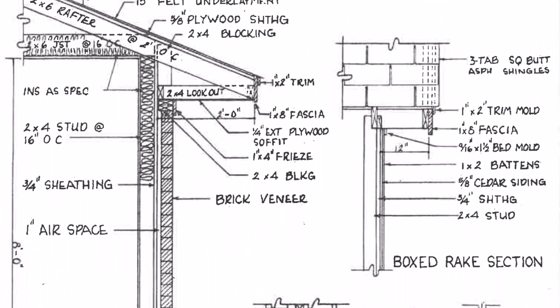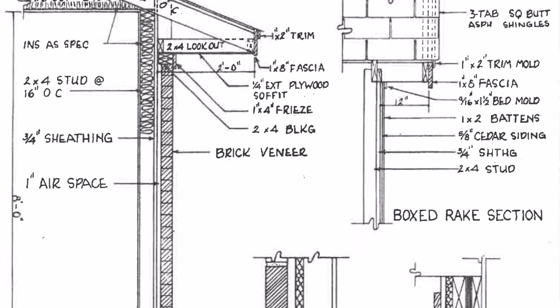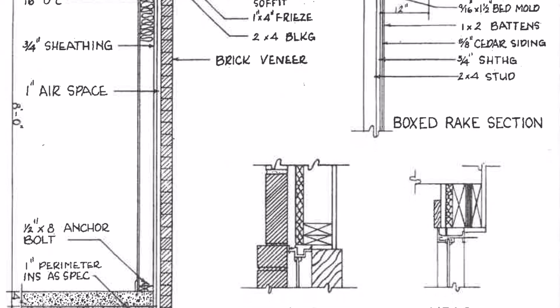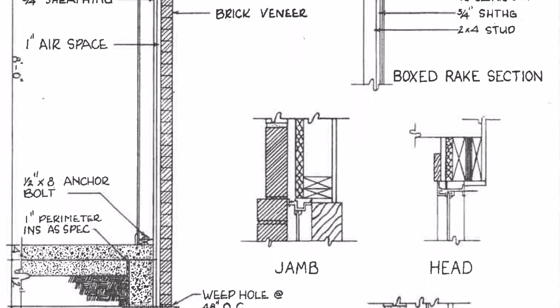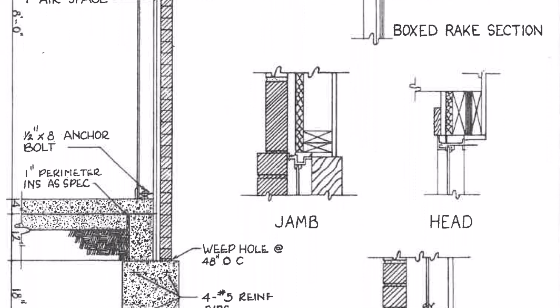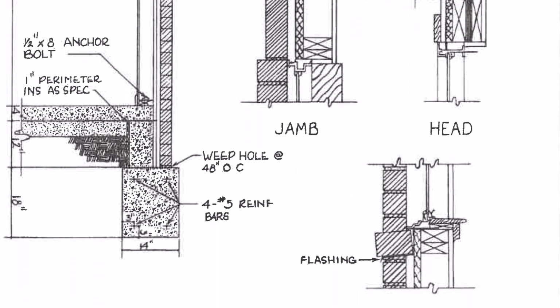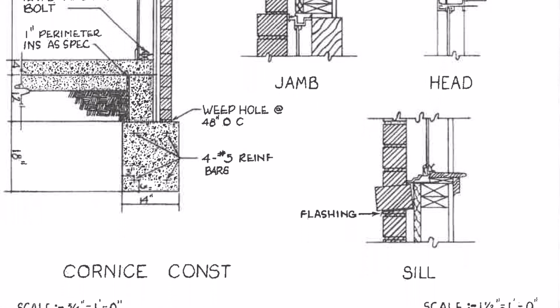You will find the general layout and information from the surveyor on the plot plans. Items like foundation plans and schedules are in the architectural and engineering drawings, and any details for custom features or unusual designs will be in the mechanical, plumbing, electrical, and ductwork drawings.